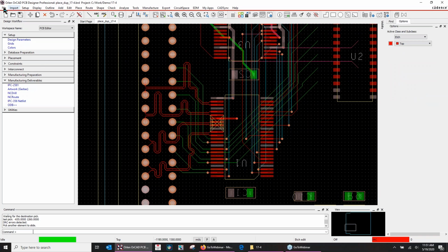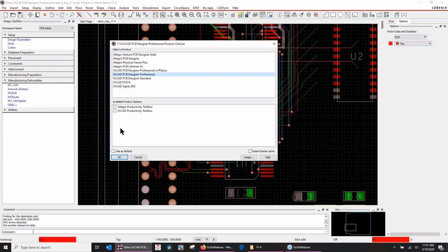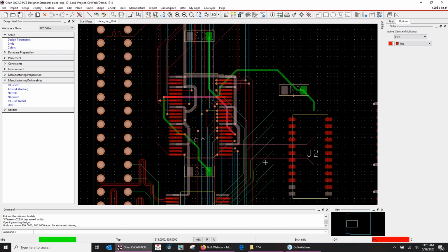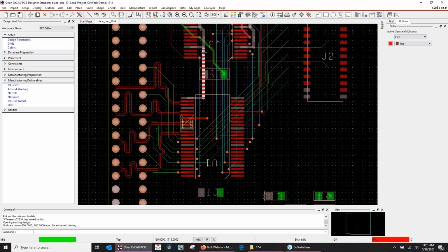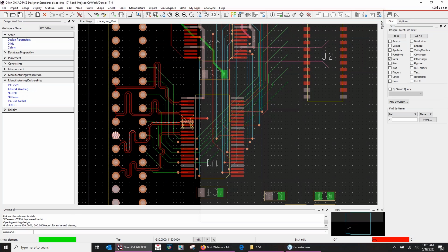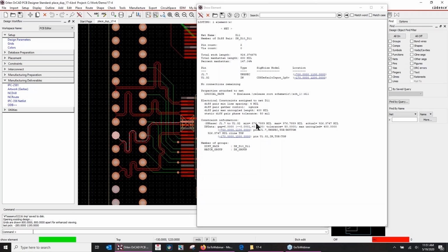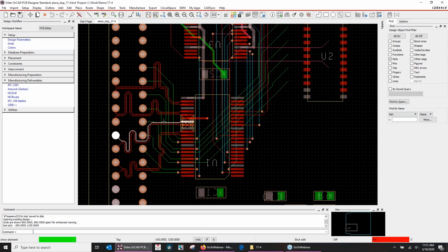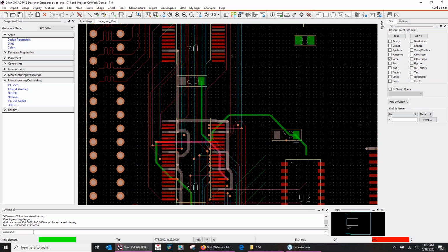Let's now get back out of this tool where we made it a little easier and go back to do some more harder work. We'll say okay. It's giving me those warnings that we expect. And again, in order for me to tune this, I would have to go in there and identify it, say what the net is and click on it, and then find out where I'm at, min, max, and the actual, and adjust that accordingly. I'd have to keep going back and forth because I do not have my little pop-up meter telling me that I'm good. You can see where it saved a lot of routing time by doing that.